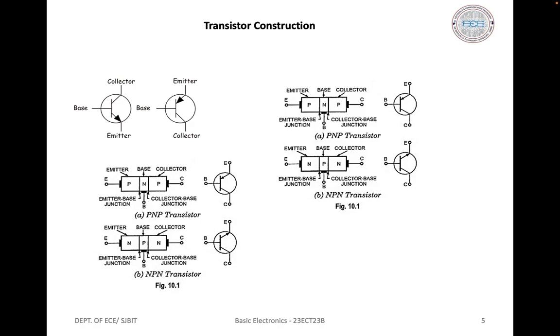This bipolar junction transistor has 3 layers of semiconductor material. These are arranged either in an NPN sequence, that is N-type, P-type and N-type, or in a PNP sequence, that is P-type, N-type and P-type. Each of the 3 layers has a terminal. A small current at the central region terminal controls the much larger current, or we can say the total current, that flows through the device. This means that the transistor can be used for current amplification. It can also perform voltage amplification.